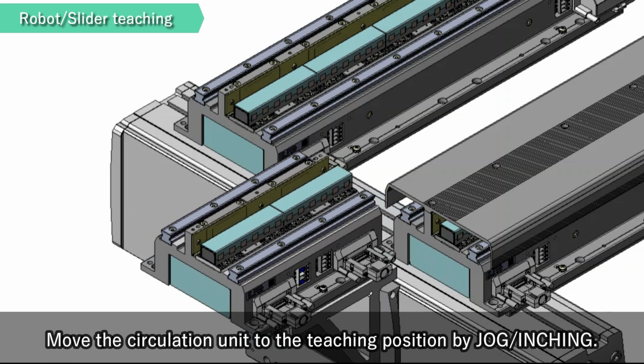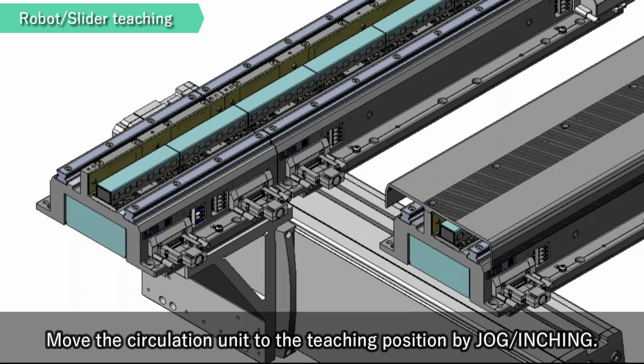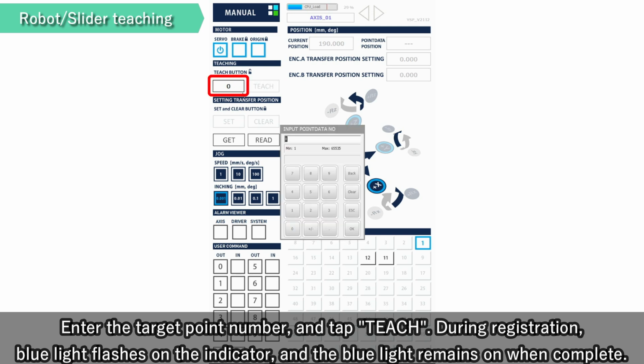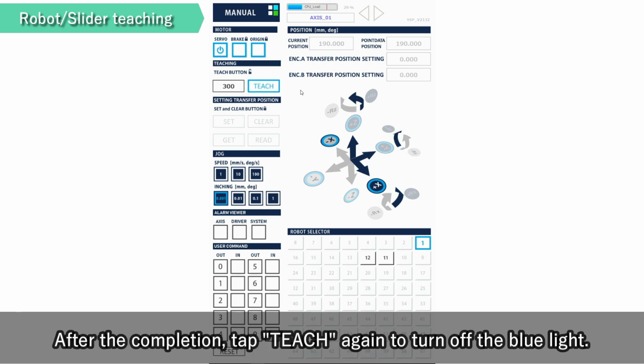Move the circulation unit to the teaching position by jog or inching. Tap Teach button and unlock the function. Enter the target point number and tap Teach. During registration, blue light flashes on the indicator and the blue light remains on when complete. After the completion, tap Teach again to turn off the blue light.